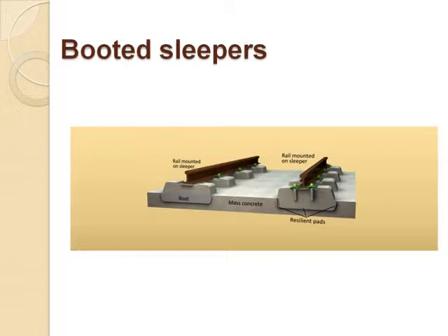The problem it has is the ingress of water. Since the structure is complicated, tiny spaces occur between each part. With these spaces, water can penetrate between boot, sleepers, and the concrete surround. Of all kinds of damages, water ingression is the most unlikely to be noticed, but the most dangerous one. It will cause the wear and deterioration of the concrete surfaces and affect the stability of the rail. The only solution now is to put polyurethane on the surfaces to avoid water ingression, which can be another extra cost.